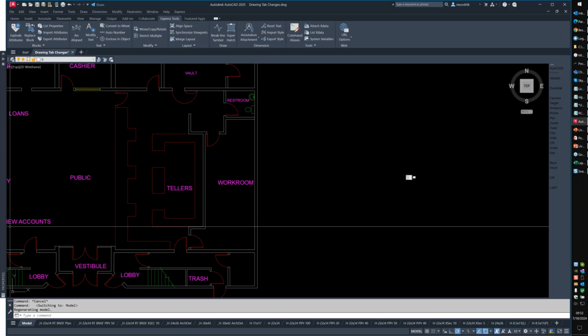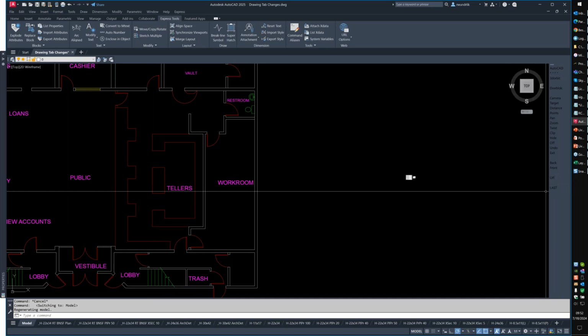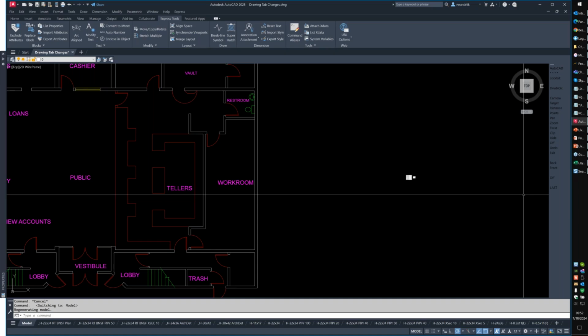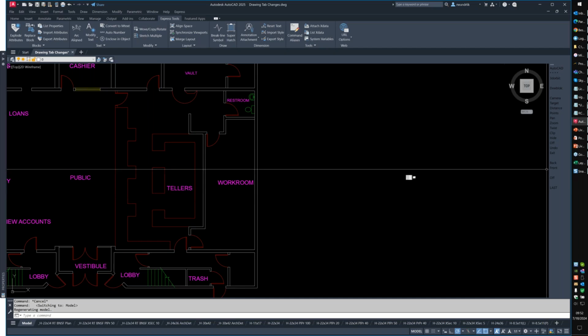You said with both sidebar menu 1, AutoCAD and AutoCAD Architecture, the right tab showed up blank with nothing. AutoCAD Architecture will not have it because this only lives in AutoCAD, and AutoCAD Architecture does not load the acad.cuix. AutoCAD Architecture runs under its own ACA, which does not have the sidebar menu. If you needed it in AutoCAD Architecture, you would need to add it there. It should be here for basic AutoCAD.